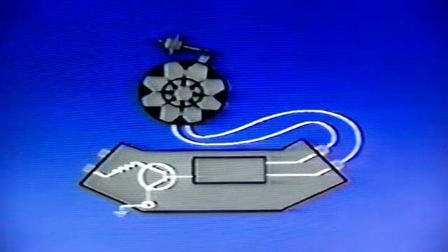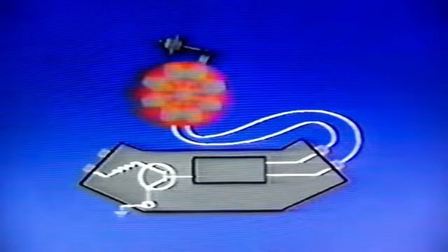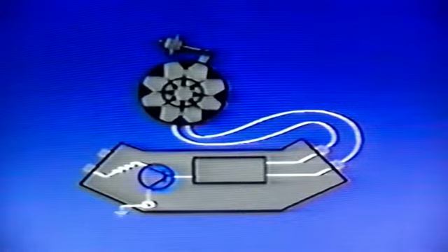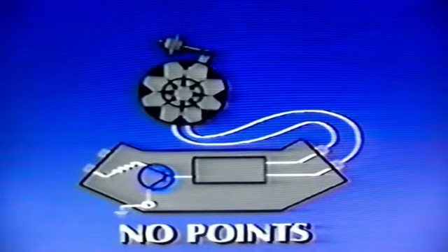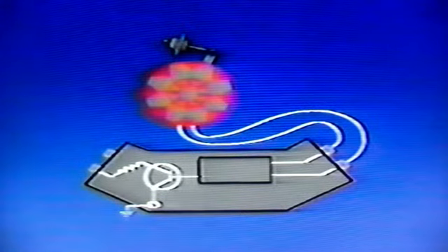One of the most important components in the module is a pickup coil, which provides RPM and crankshaft data to the ECM. The way this works is that the pickup coil sends out a pulse signal which triggers a switching transistor that replaces ignition points. The end result is that instead of the points opening and closing, we now have a much more dependable transistor to do the job. Timing is controlled by the pickup coil through vacuum advance and centrifugal advance. If anything changes at the pickup coil, the ignition time will change accordingly.